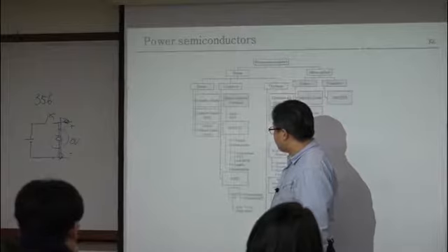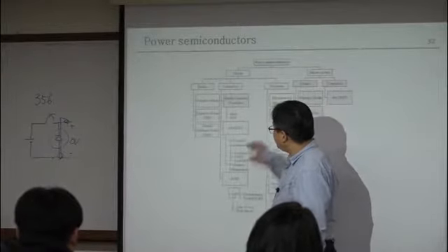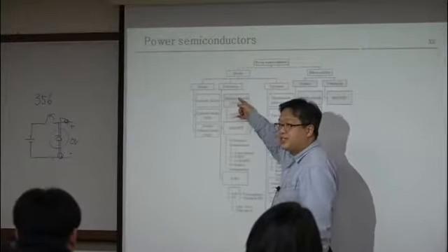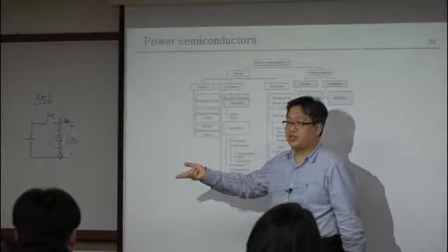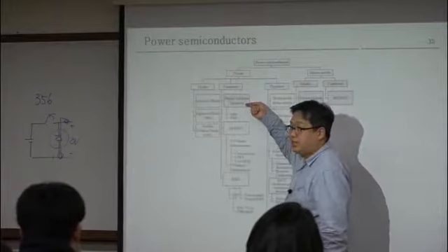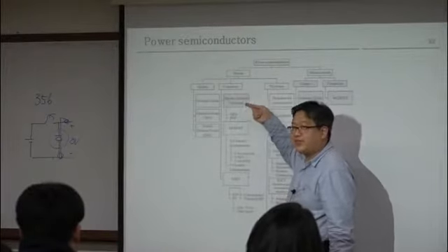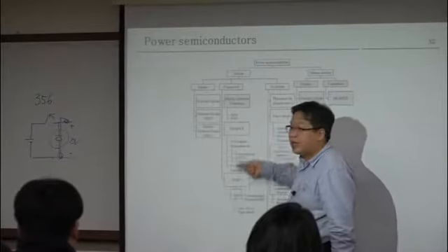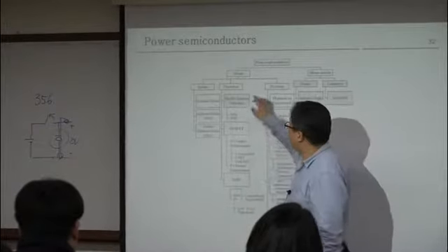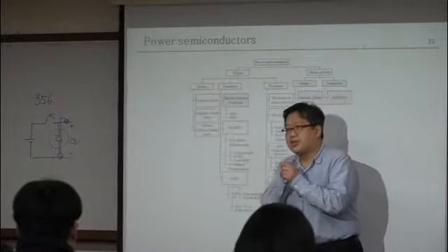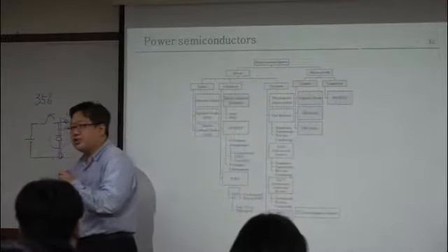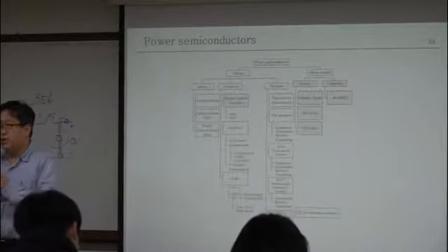So we use MOSFET and IGBT recently, and we may not use BJT for new designed circuit, because the BJT driving technology is difficult, and their efficiency is not as good as MOSFET or IGBT. So for very small power or small signal conditioning circuit, you use BJT, but for the power electronic circuit, you don't use BJT. Okay?